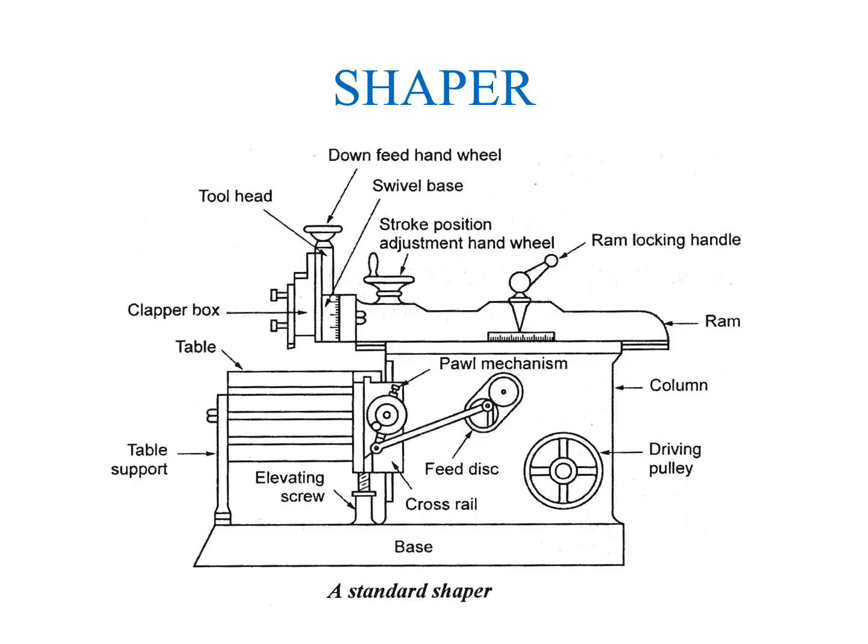Next, shaper machine. First, the shaper is a machine tool used primarily for producing a flat or plane surface which may be horizontal or vertical or an angular plane, and it is used for making slots, grooves and keyways. It also produces contours of concave, convex or a combination of these.